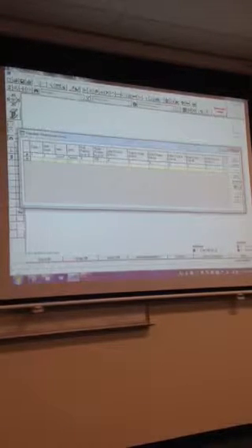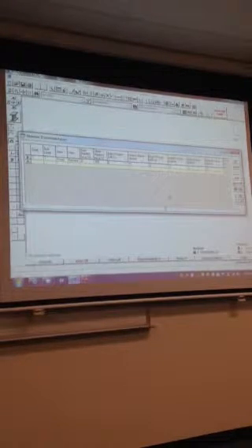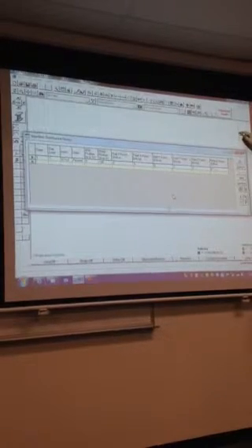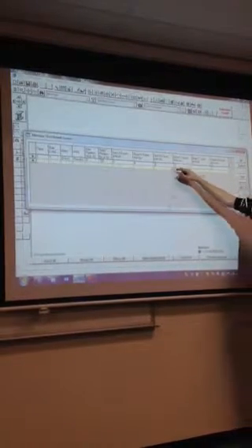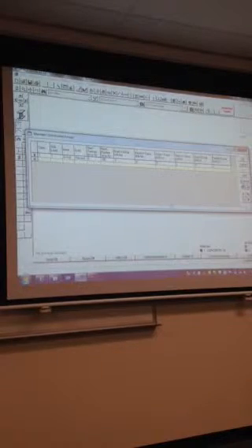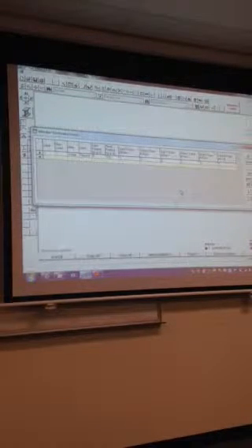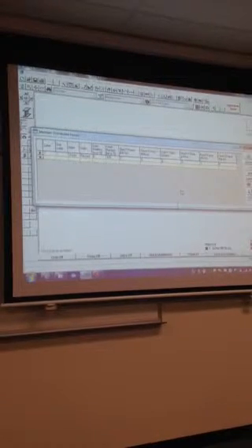Load case 1 we said is going to be called dead loads. Remember, we're only going to put in the dead loads, which are in addition to the self-weight. In that case, that's 1 kPa. Looking at direction up here, Y is up and down. So we're going to put in a starting force and an ending force in the Y direction. Gravity's down, isn't it, but our positive Y is up. So do we put in a minus number there or a positive number there? It'll be minus. So we're going to put in -1 because that's our additional.